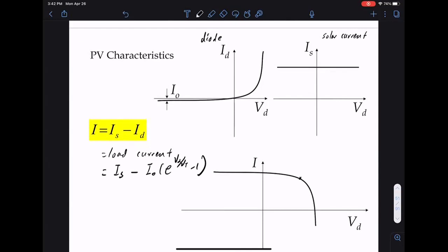Okay? Yeah, this is the graph you get, right? So since we get to set VD, you want to set VD at a reasonable value, right? You don't want to operate in this region, for example. You don't want to have negative VD on current, but you also don't want your VD to be very large and you're pulling negative current. Right? So you want to operate in the correct region for VD. Any other questions for these curves?